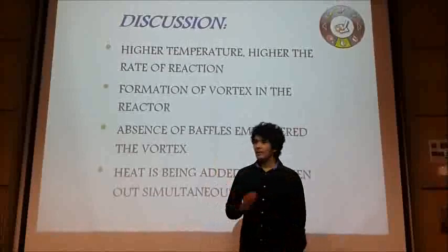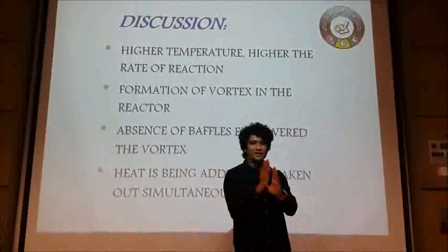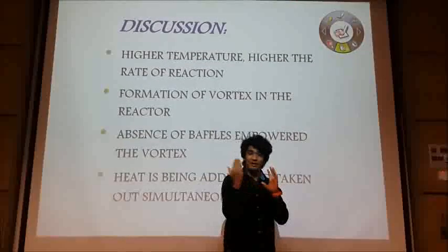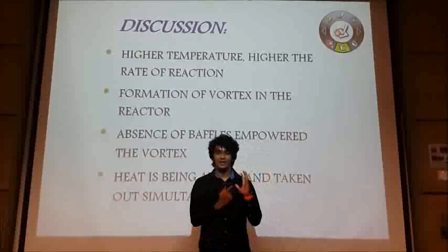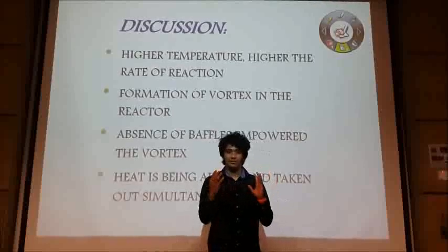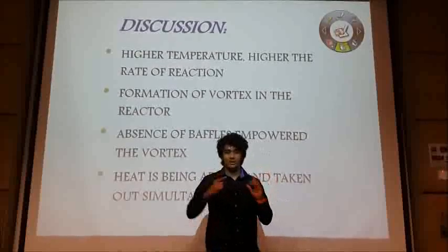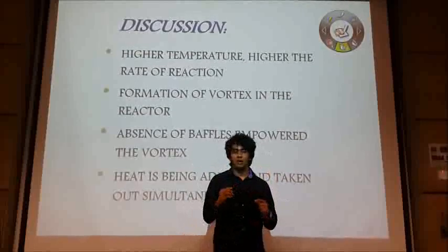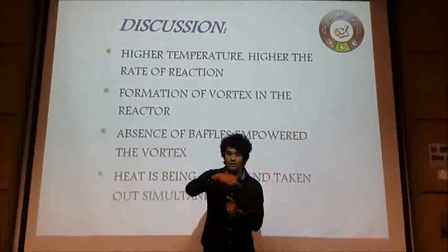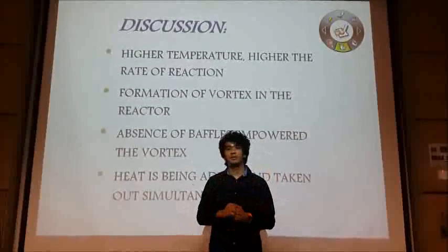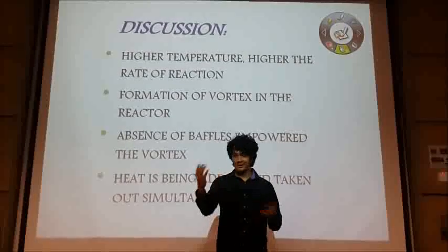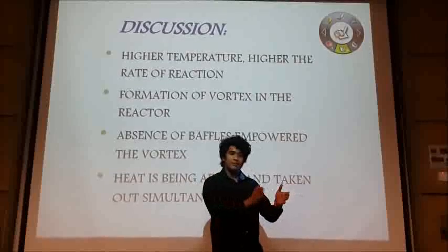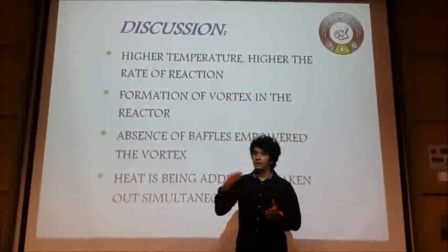A vortex will actually push the particles to the walls of the reactor, so the particles on the outside will not react. Furthermore, a vortex will make the angular velocity of the particles different according to how close they are to the stirrer. This creates the pushing effect of the particles to the glass wall.